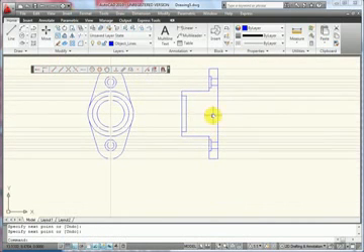And to finish off this side view, you draw the through holes for here. Normally these would be hidden lines, and you'd also normally see a line that would connect these two. However, this is going to be a section view, so we actually want to be able to see those through holes. So in this case, this would be exposed, and this would be the material surface right here.